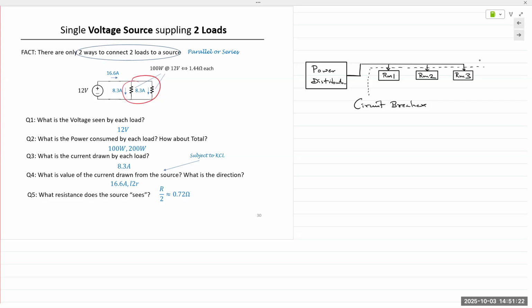If a fault occurs at the end of the line and it's trying to pull a large amount of current through the fuse wire, guess what? The wire gets hot. Because it gets hot, it melts, and the circuit is broken. We say the fuse has blown out. So you have to take the fuse out and plug a new one in, and so we have to keep a stock of fuses. Thankfully, that doesn't happen as often as it used to.